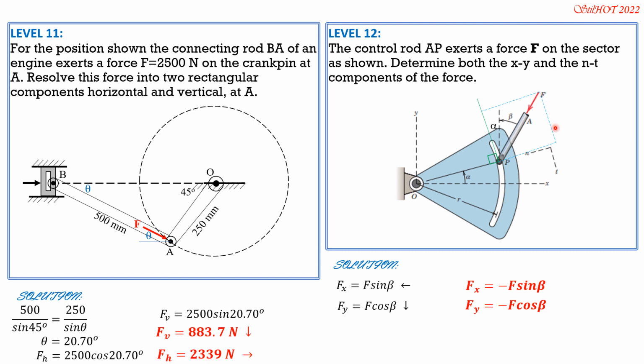And this is Ft, which is equal to this, also in the direction of the tangential axis. So both are positive. For Ft, which is adjacent to alpha and beta, it is F cosine of alpha plus beta. So that's Fn, and this is Ft, which is also equal to this. So again, Fn is in the positive direction, and it is opposite to alpha and beta.